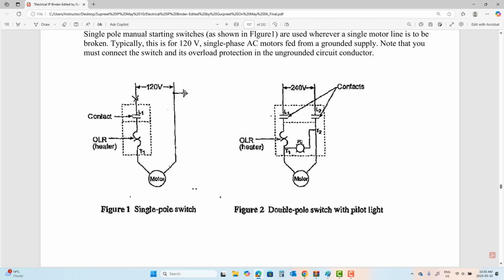And the breaker, what does it do? It has a bimetallic strip. It expands in the event of heat. Same concept here. Those are called OLRs right there. So in the event of heat, we don't call it on-off. We call it energizing and de-energizing of the relay. The relay gets de-energized, and now the contact will open, the motor will shut down. That's how any motor overload device works.